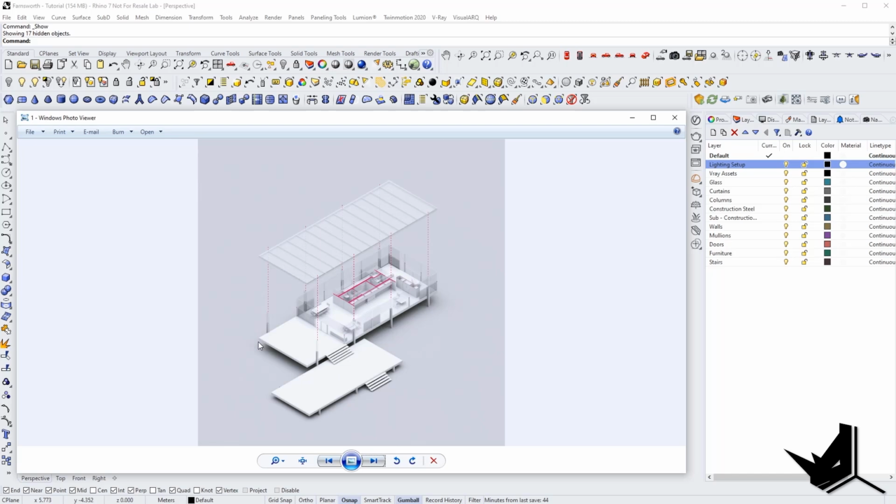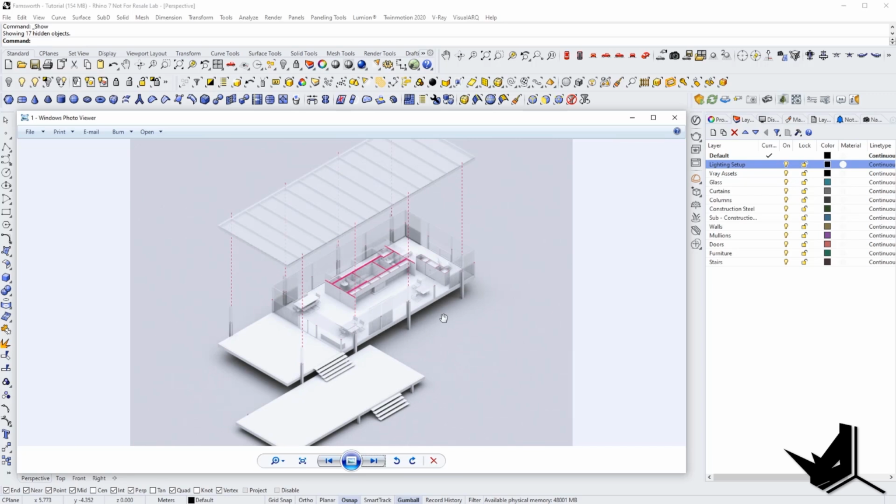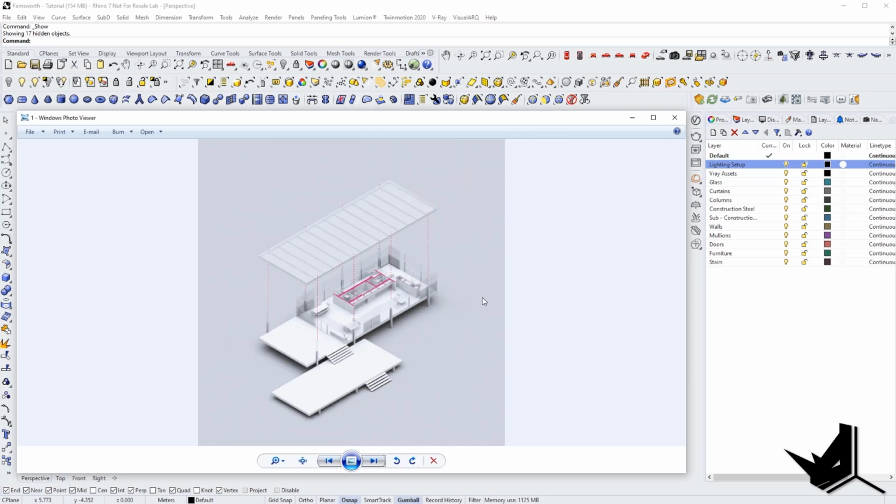And sometimes if you just want to get this kind of nice effect without sharp shadows, I prefer to use HDRI images, because HDRI images can really give you this effect. But you also need to pay attention that you don't use just any HDRI image. You want to use an HDRI image that has some kind of cloudy weather, and that's going to give you this kind of effect.